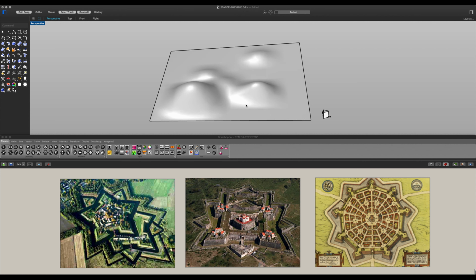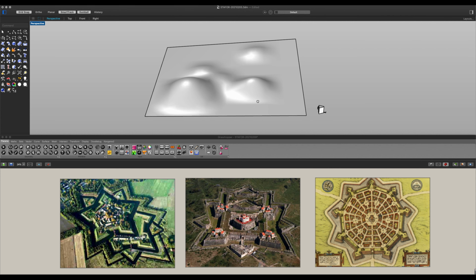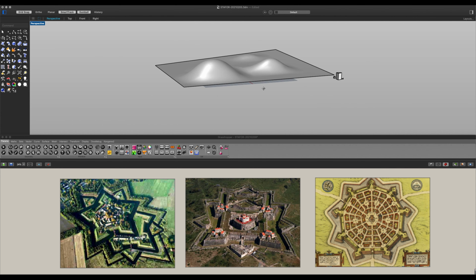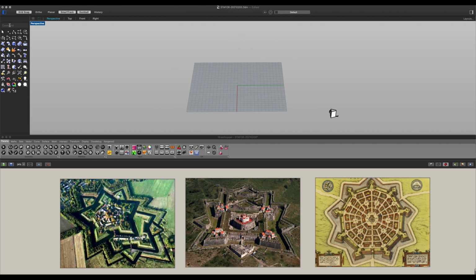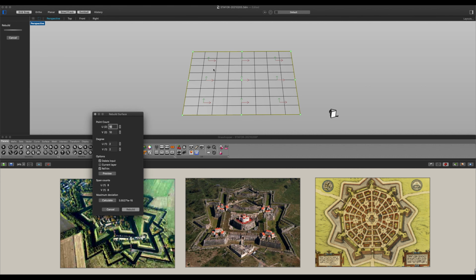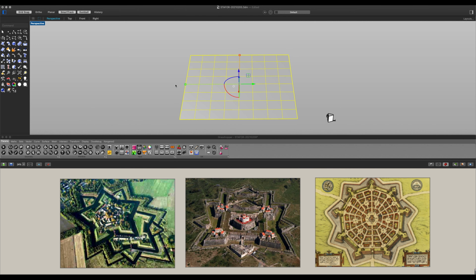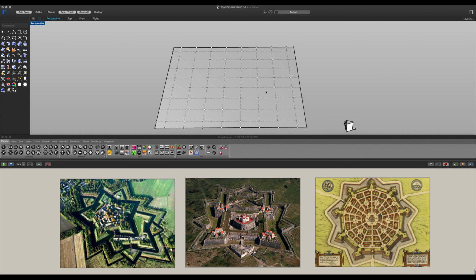And the first thing I want to talk about is the Rhino elements. For this exercise, you want to get yourself a new surface, as I'm doing here with this surface from 4 points. Next up, you want to rebuild this surface. I'm gonna go for about a point count of 10 by 10. That should be enough. And then you want to activate your points like this.